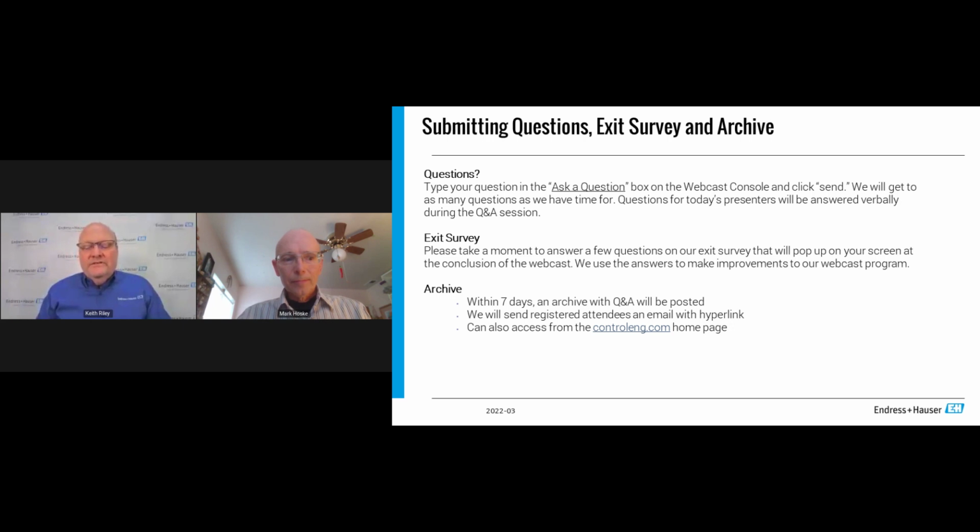So again, if it's simply costing us a lot of downtime, we're obviously going to start to talk about verification, where that's practical, where it's not, depending upon what the service is, what they're trying to do with that part of their process. If we're going to look at things like foam detection, we go through thousands of dollars a month every month because we have a foam issue, and we are eating up our maintenance budget in defoaming agent. Then we can have that discussion with some of our level measurement technologies.